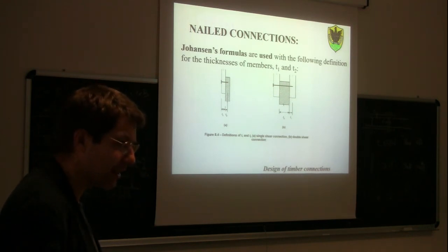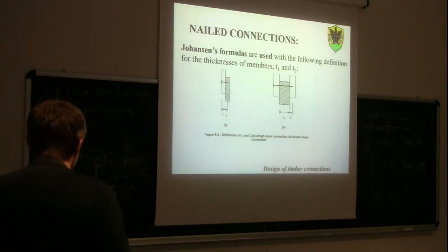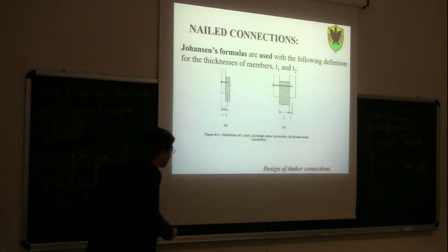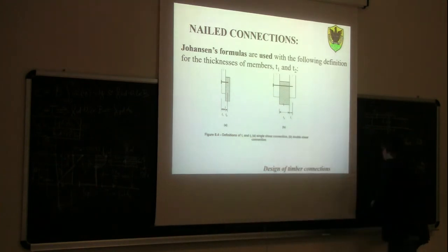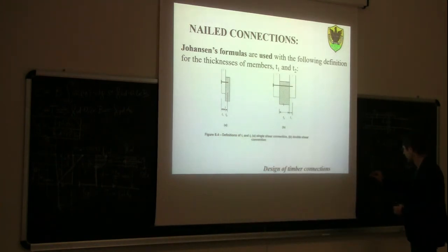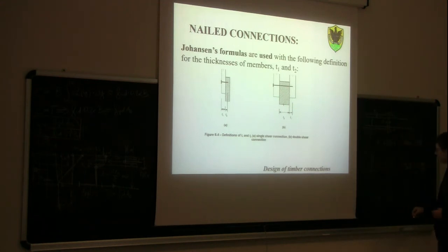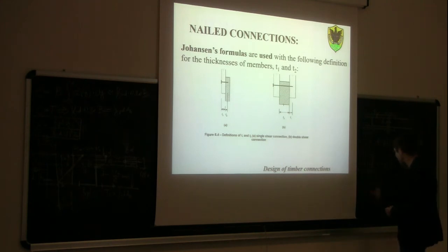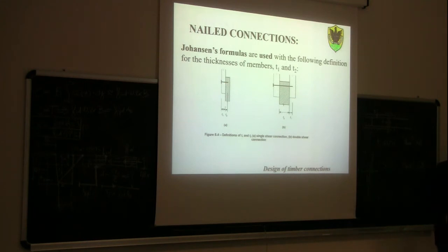Since they have a very small diameter and a pointed tip, once you insert them, suppose your wood is oriented this way, they just part the fibers, so they just enlarge the fibers, and they don't directly break the fibers. Instead, a self-tapping screw is going to cut the fiber. It's going to cut and take the shavings outside. Okay?